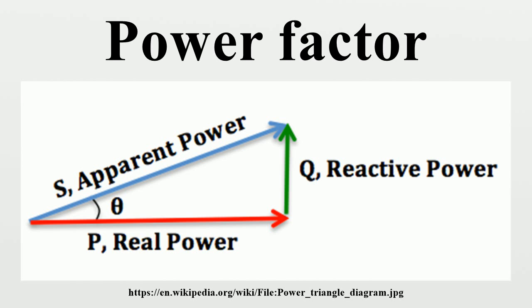The condenser's installation and operation are identical to large electric motors. Its principal advantage is the ease with which the amount of correction can be adjusted. It behaves like an electrically variable capacitor. Unlike capacitors, the amount of reactive power supplied is proportional to voltage, not the square of voltage. This improves voltage stability on large networks.